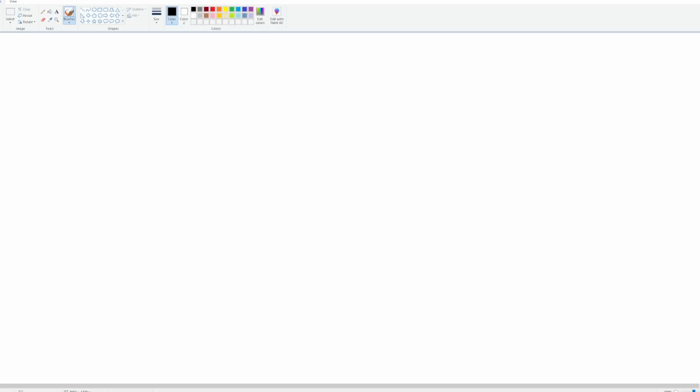First thing, I would like to show you here what I'm talking about, okay? So we have the runway here, and in green, we have our 3-degree path up until our altitude, 2,000 feet. And in blue is our mean sea level, okay? So this is where we expect the ground to be. This is our runway. And this is our 3-degree glide path with the sample line there.